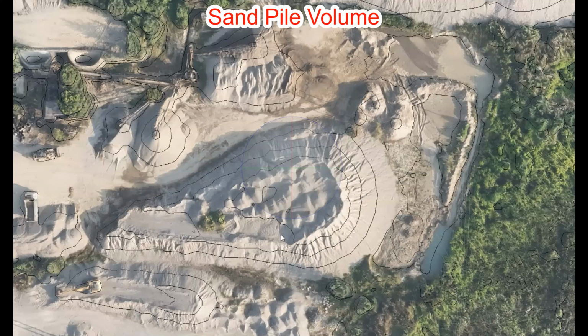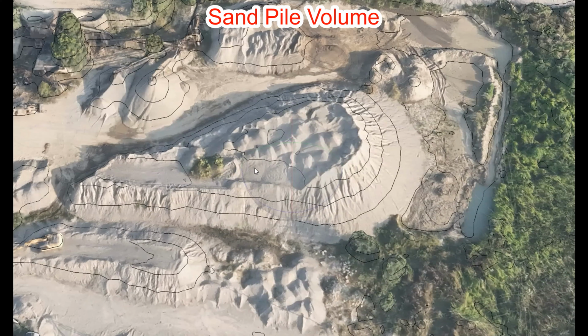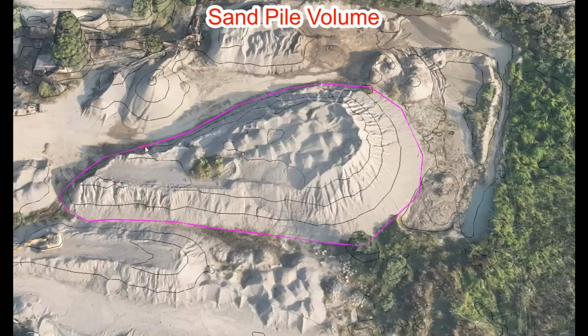For example, if you want to calculate the volume of this sand pile, for this particular sand pile, then what we can do is go to draw polygon, and I just want to draw the polygon. Okay, this is my polygon. Double click. Okay, this is my polygon.